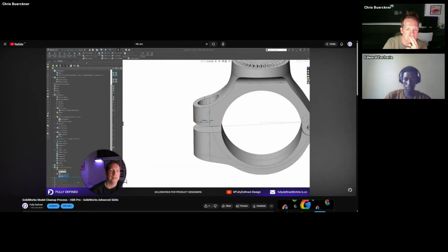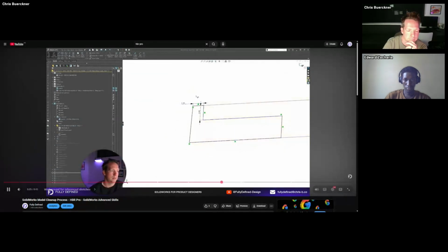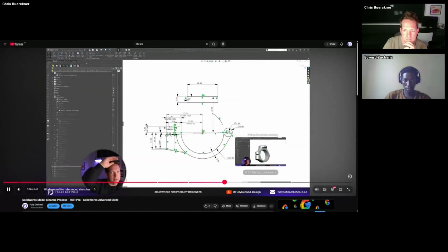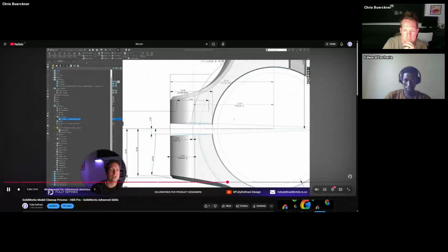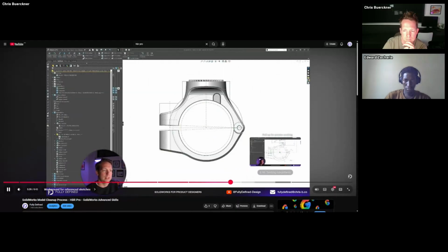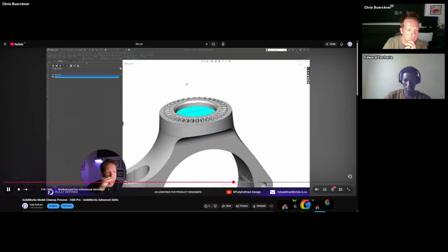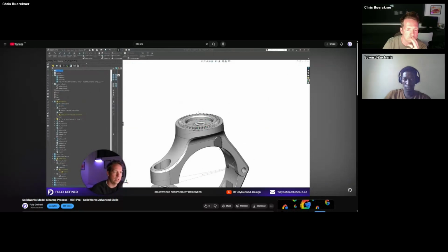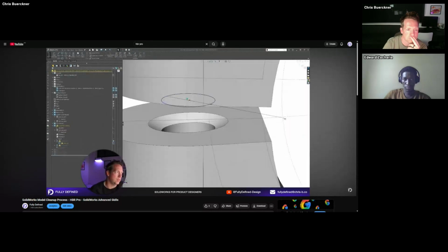And then in my key driving sketch, which would be one or two steps below that, I can redraw that sketch element, but now give it relations within that driving sketch. So I'm basically copying a sketch element that's down low, moving it all the way to the top to my driving sketch, and then re-adding relations within that sketch to the rest of the model, the rest of the elements, or the origin. Once you've done that, you go back to the feature driven by that sketch and change the reference from the original sketch to the new driving sketch. With that done, you can now delete the obsolete sketch, and your model is one step closer to perfection.